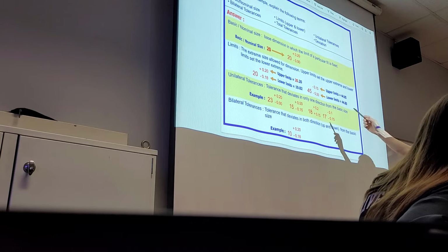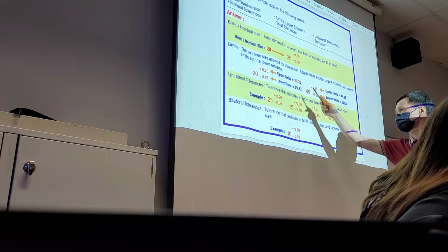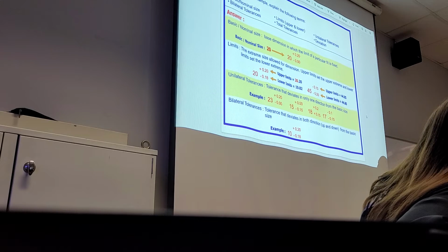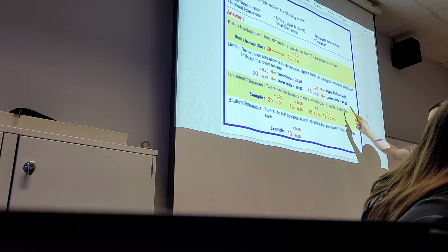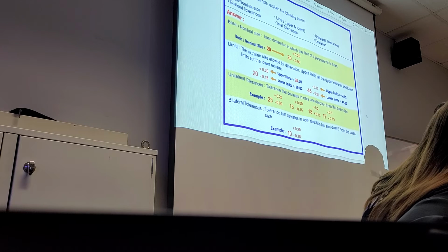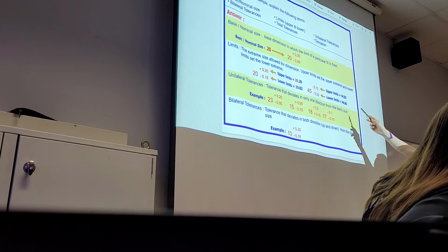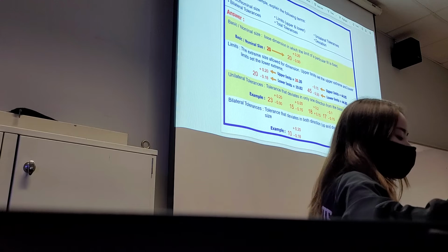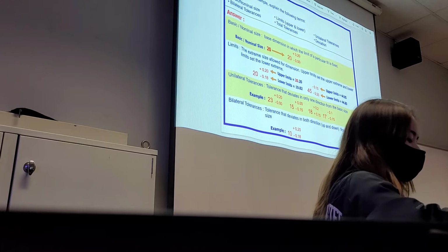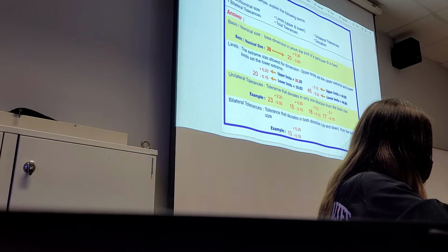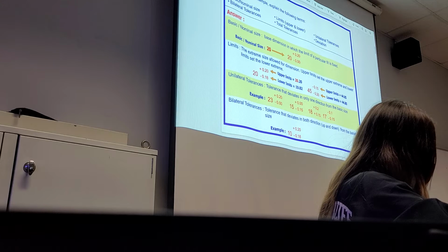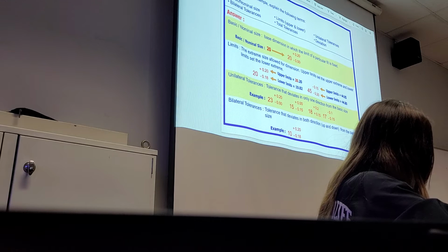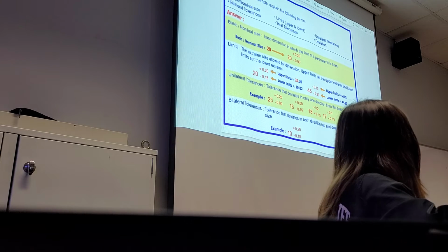Normally in the drawings, we will use this way to specify, a very clean and neat way. But we understand the lower limit is like this, the upper limit like this. They write these two because it's very clumsy, not so easy. And then the QC job is basically to check each of our individual parts within this range. So this tolerance can be one direction, can be bi-direction, doesn't matter. Not critical.